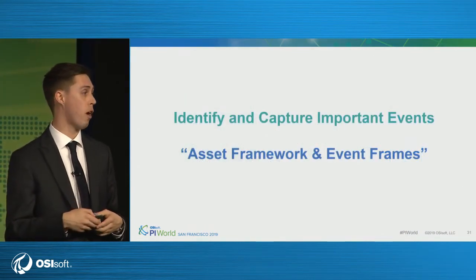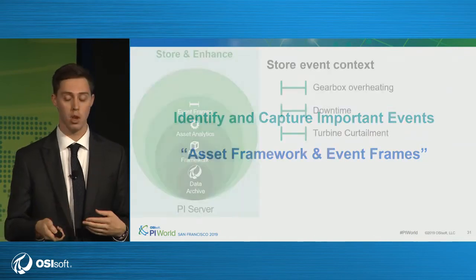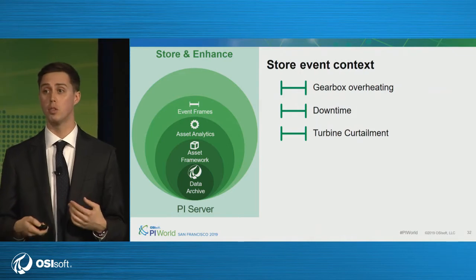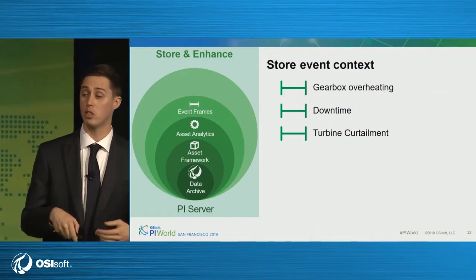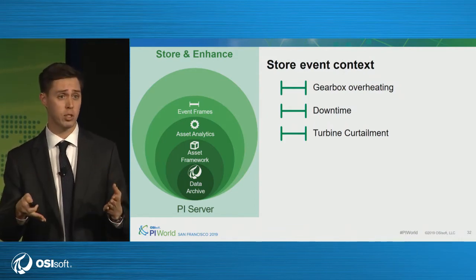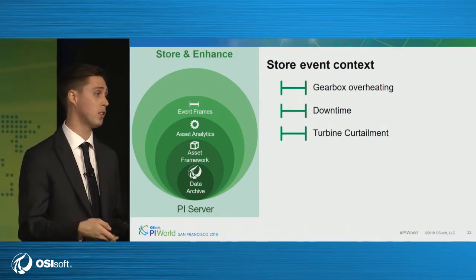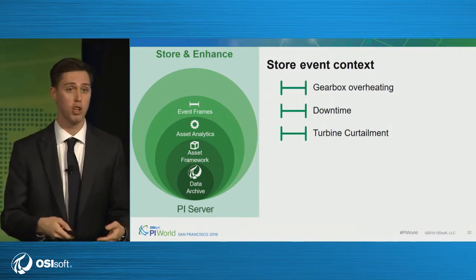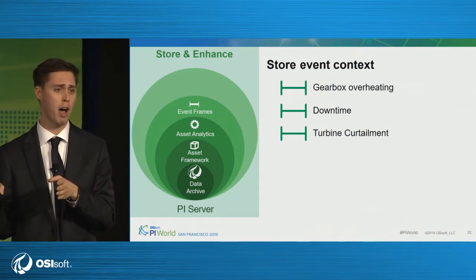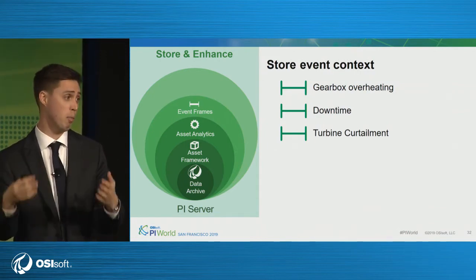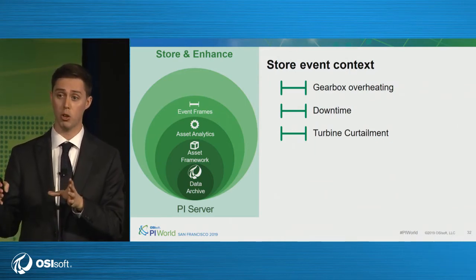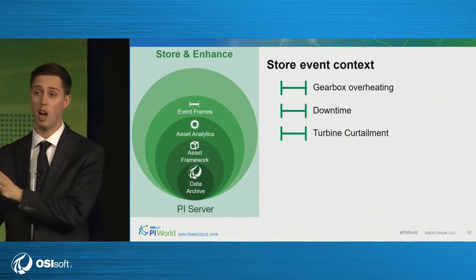Next, we'll go into how to identify and capture important events. So we add on another layer to the Pi server, and that's our event frames. So you might have heard Chris Nelson talk about this in his talk, which is if you ever have an event of interest, in our example for the wind turbine, it's a downtime event, right? You might want to set aside that period of time and capture a certain number of values, whether it be the temperature, the pressure, any of these operational data measurements that you want to capture in that time period. You can just set it aside as an event frame.